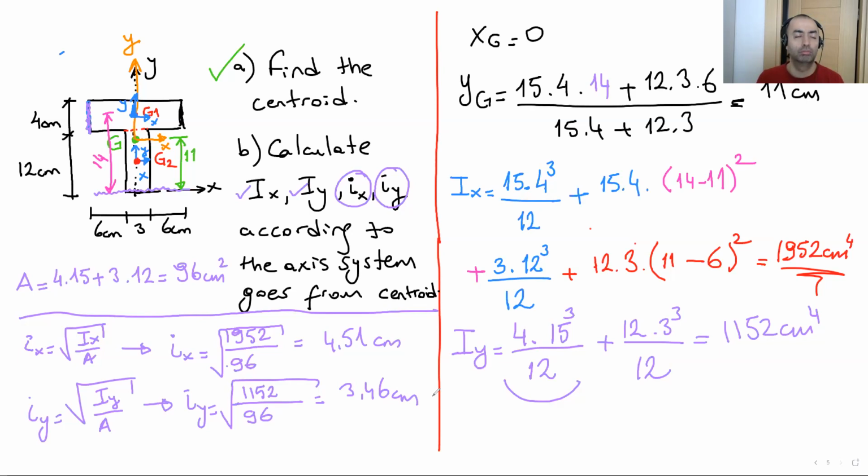While you are studying, you need to get a better understanding of when we shift or transfer a local moment of inertia to a global one, and when we don't. If you understand these differences, you can solve each type of problem.